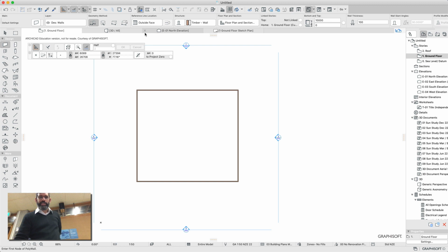This doesn't work for that last setting. If you're drawing a straight wall, right? So let's say we're just going to do a straight wall. Now you've got to be very careful because we're drawing a vector, but our wall has thickness to it. So if we draw the inside of the room, but we'd actually measured the outside of the building, there's going to be a discrepancy. If I wanted to split a room in half, I'm going to have to make sure that my wall goes on either side of the line that I draw, because otherwise I'm going to make one room smaller than the other. Does that make sense?